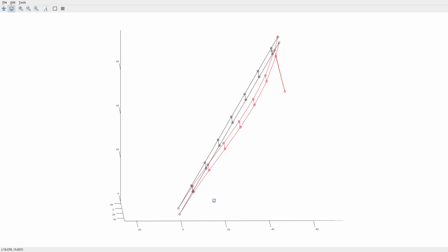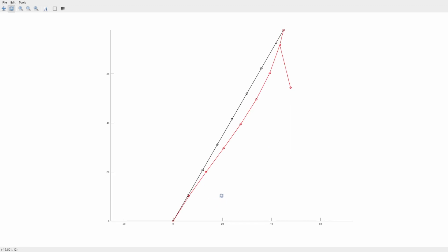And you can see with this linear analysis, because we took one time step and multiplied it by a factor of like 50, it's a little bit wonky here, right? The guy is stepping down. Why is this location moving out in the z direction like this? Well, that's because it's a combination of a rotation and a displacement.